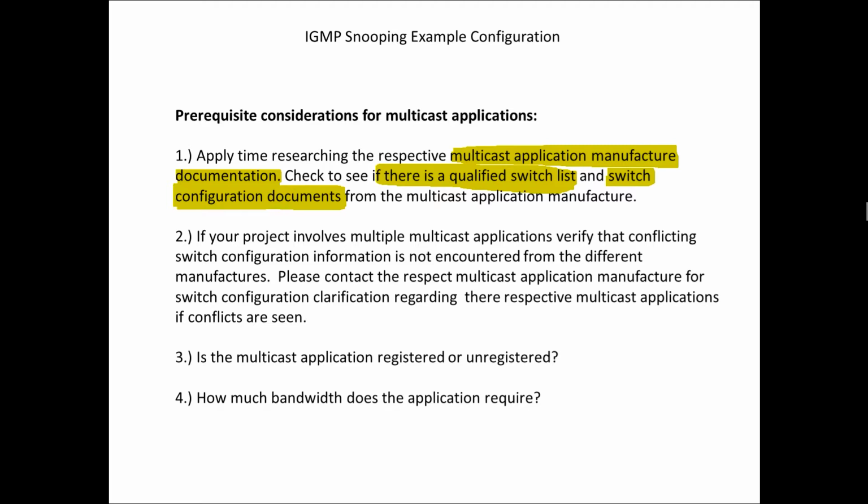Most of the pro audio video applications have very tight tolerances regarding latency, jitter, and packet loss, and it typically tends to be exponentially tighter when compared to something like VoIP. Generally, with the pro audio video applications, we're dealing with the microsecond domain from a timing standpoint, and with VoIP, we're dealing with the millisecond time domain. So it's exponentially different timing domains.